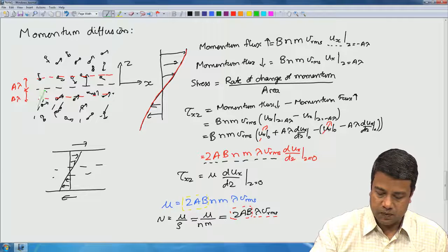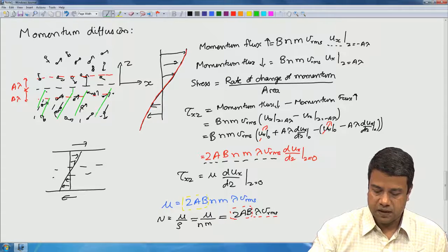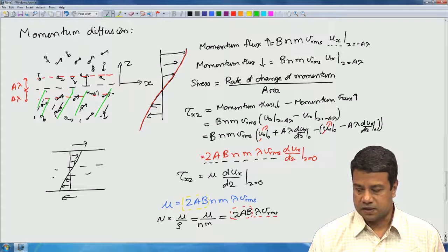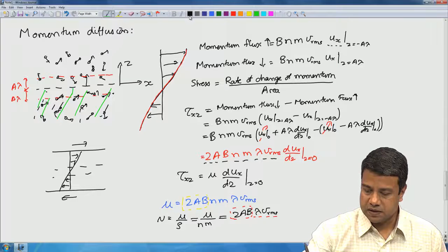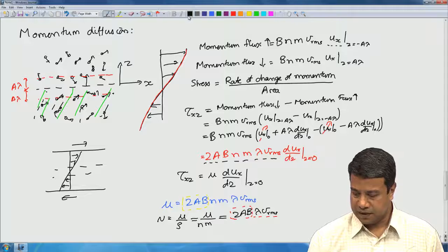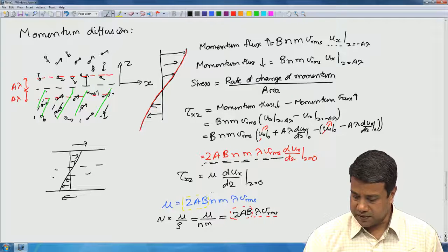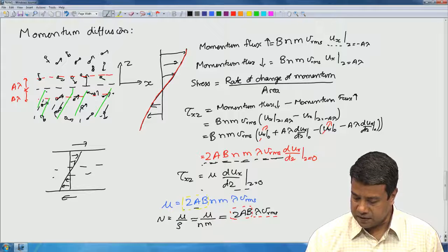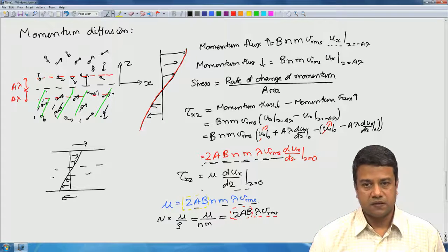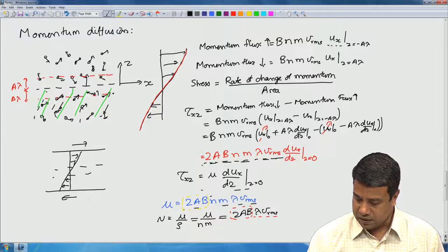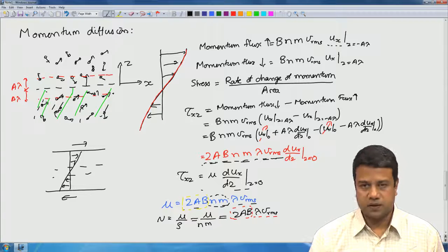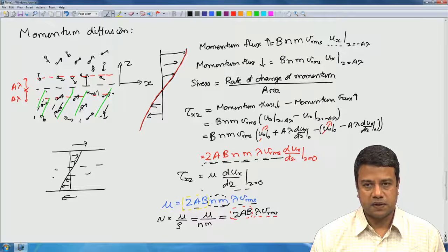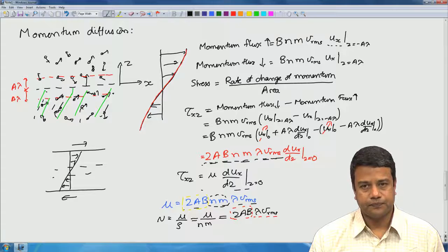That corresponds to the volume below the surface, because for this volume the outward unit normal is in the plus z direction. On that basis we had calculated the momentum flux across the surface, and compared that with the expression for Newton's law of viscosity and got an expression for the viscosity coefficient itself. The viscosity coefficient is equal to the number density times the molecular mass, which is the mass density, times the mean free path times the RMS fluctuating velocity.